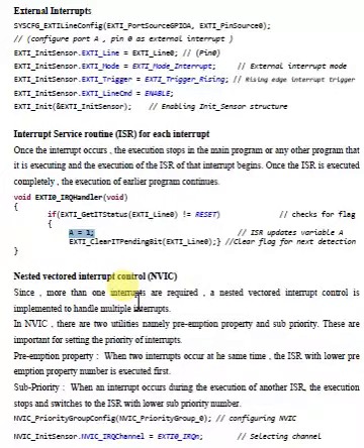Similarly, with a sub priority, when the interrupt occurs during the execution of another service routine, the execution stops and switches to the ISR with the lower sub priority. These are very useful in scheduling, let me say, and also in situations where we have prioritization of the different interrupts.